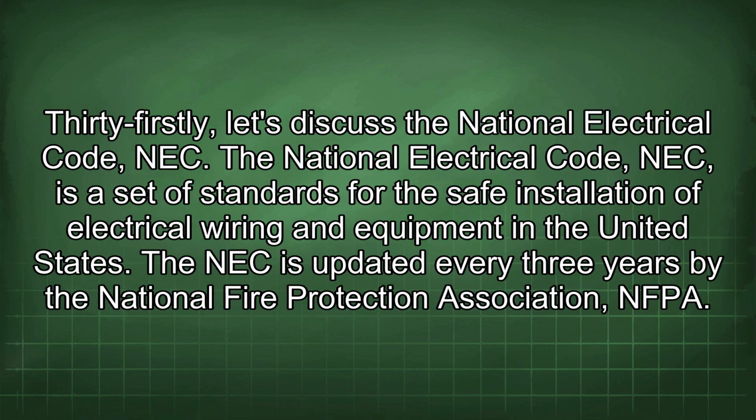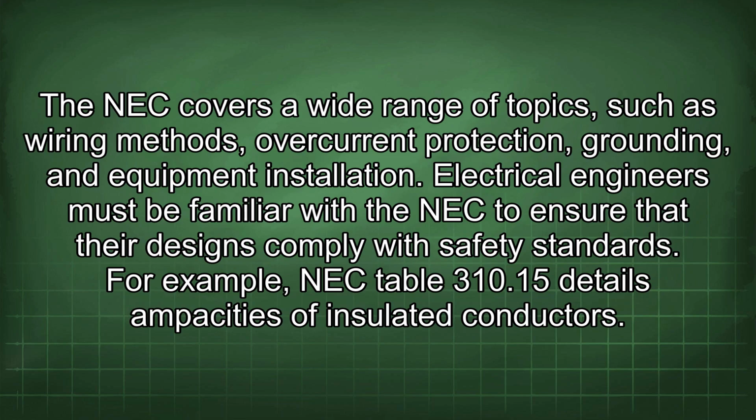Firstly, let's discuss the National Electrical Code, NEC. The National Electrical Code, NEC, is a set of standards for the safe installation of electrical wiring and equipment in the United States. The NEC is updated every 3 years by the National Fire Protection Association, NFPA. The NEC covers a wide range of topics, such as wiring methods, overcurrent protection, grounding, and equipment installation. Electrical engineers must be familiar with the NEC to ensure that their designs comply with safety standards. For example, NEC Table 310.15 details the ampacities of insulated conductors.